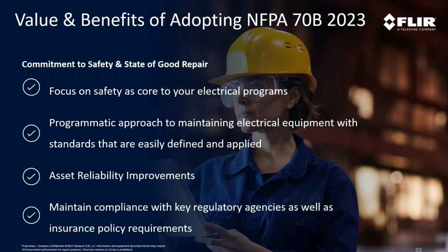And particularly with 70B, where you're performing these tests under loaded conditions, you're going to have cabinets open, or even better, you're using IR windows in these cabinets to be able to do your scanning. But safety is really going to be a core to developing a strong program.